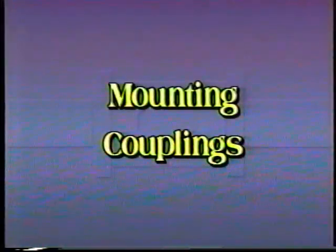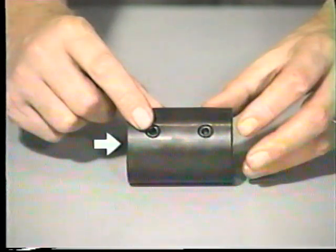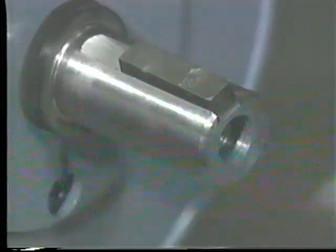No matter what kind of coupling is used, the coupling halves must be mounted on the shafts being joined. Most coupling halves are bored out, so the hole is slightly larger than the shaft. Typical clearance is 1 or 2/1000ths of an inch. Sometimes one side of the shaft is flattened, and a set screw holds the coupling in place on the shaft. In most cases, however, a square key is used to keep the shaft from rotating inside the coupling.